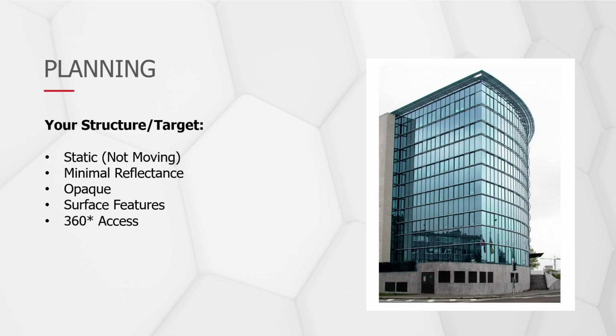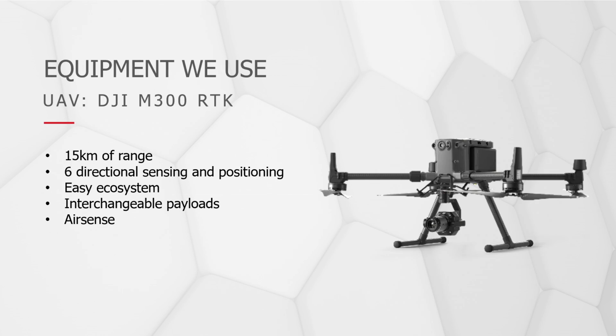Right, so something like the target, this building in the picture, for example, this would be a difficult capture? Yes, something like a glass building with lots of reflections with opposing environments. If you have those reflections of cars moving around in the scenes, then those tie points will have a hard time trying to figure out, hey, which angle is this photo located? That makes a lot of sense.